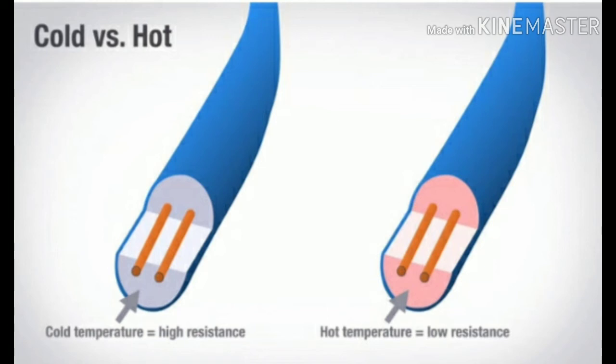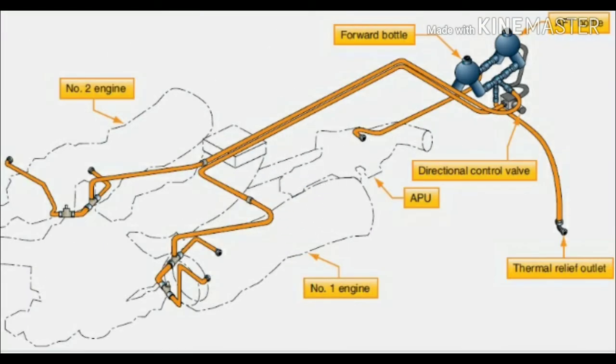Automatic self-interrogation. Dual loop systems automatically perform the loop switching and decision-making function required of the flight crew upon appearance of the fault indication in the cockpit. Automatic self-interrogation eliminates the fault indication and assures the immediate appearance of the fire indication should fire occur while at least one loop of the dual loop system is operative.